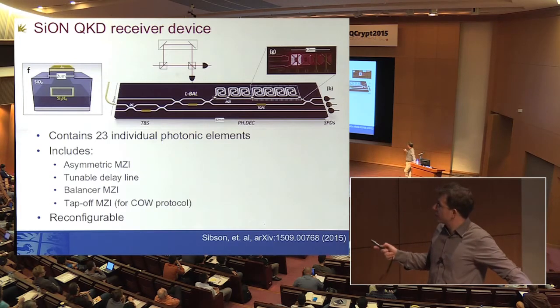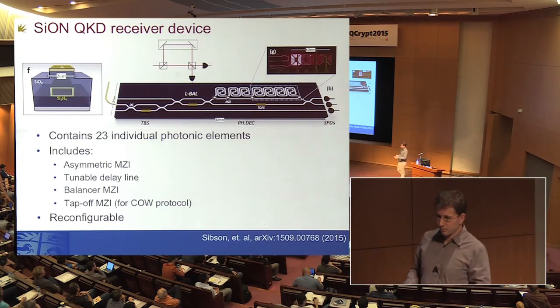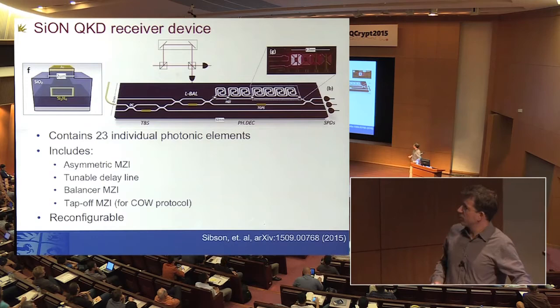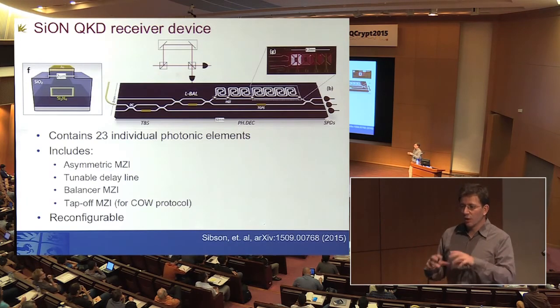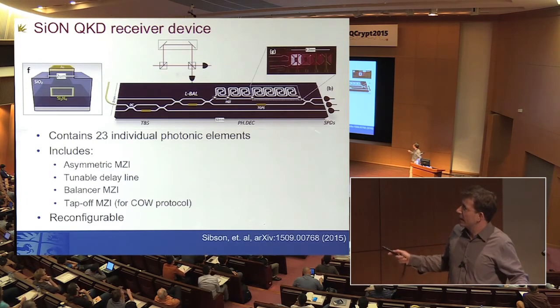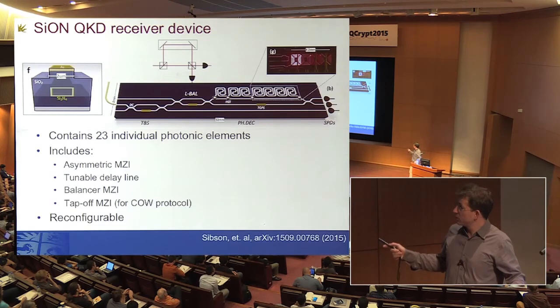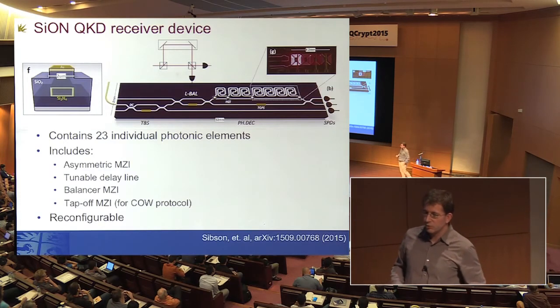So yeah, the detectors are off chip. The long-term strategy is to look at getting detectors on chip, but we're a good way from doing that. The coupling losses are because we're using a glass-based material system. One of the reasons we went for it is because of the low coupling losses. In this case, we're getting about 2 dB coupling losses, which is actually quite high for a glass-based material. Feasibly, in future devices we should be able to get that down below a dB or even half a dB. So really efficient off-chip coupling.